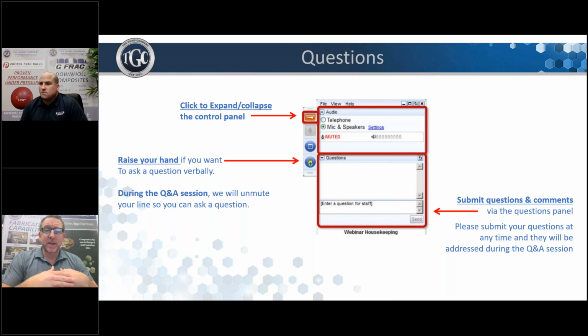If you're talking about SMC, there's also a feed rate factor. If you're chopping and feeding the gun roving into the SMC machine, you have to feed that roving onto the belt at the correct rate. Otherwise, you can end up with a fiber content problem, fiber content variation. I hope I answered that question correctly, Chris, and that answers what you're looking for.